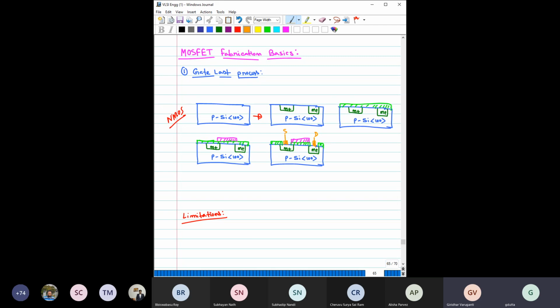Now the issue in terms of fabrication or practical realization of this device would be something like this. Say we are placing this gate metal like this. How do you do that? There is no such process, it is not an automated process, and even with automation there is some inaccuracy, because I have to place my gate exactly here. What will happen if you shift it?